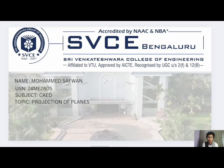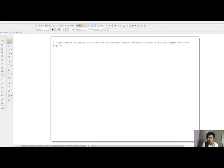In today's video, we are going to discuss problems on projection of planes from computer aided engineering drawing. The first problem we have is a square lamina of 40 mm side rests on its sides on HP. The lamina makes 30 degrees to HP and the side on which it rests makes 45 degrees to VP.